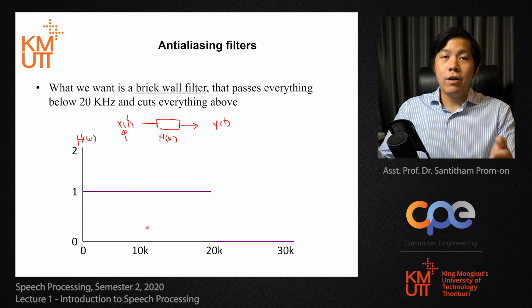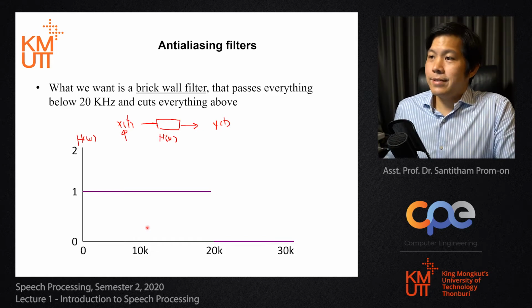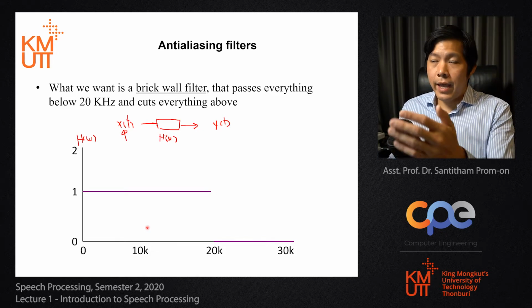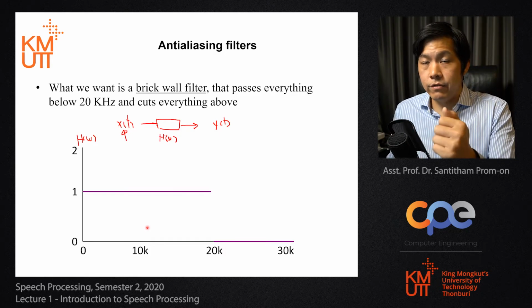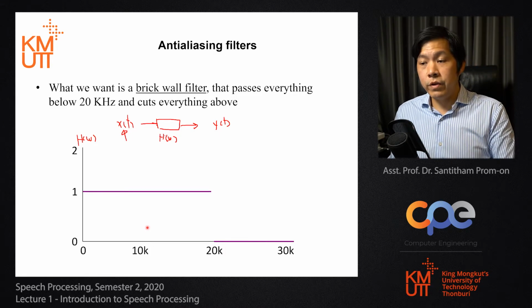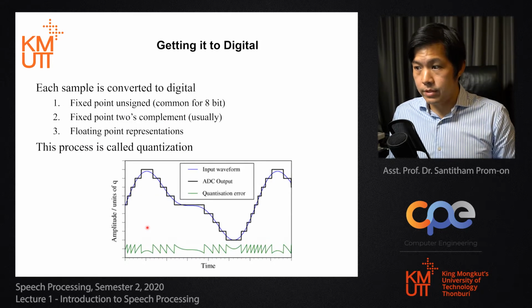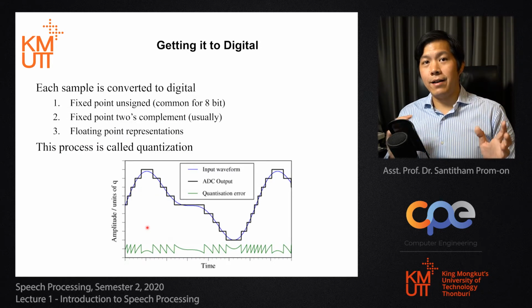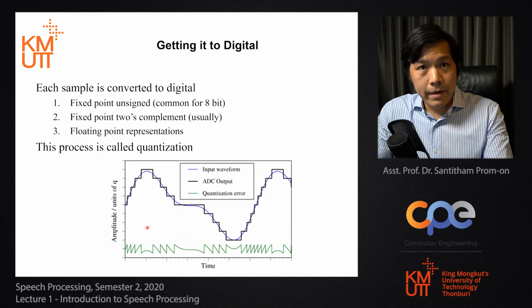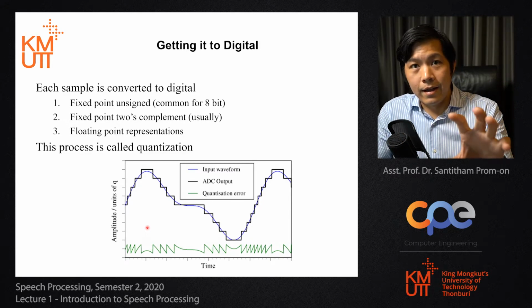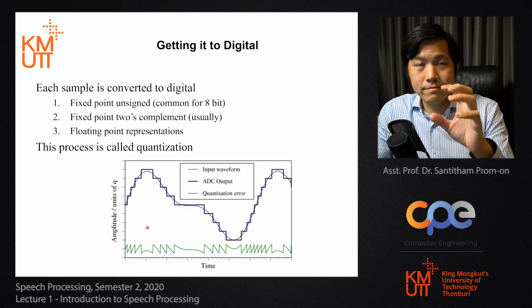This is called a low pass filter. So anti-aliasing uses a low pass filter as the method to filter high frequency content out. Okay, so that's the anti-aliasing filter. So now you have seen sampling and then getting data, but it's not done yet.